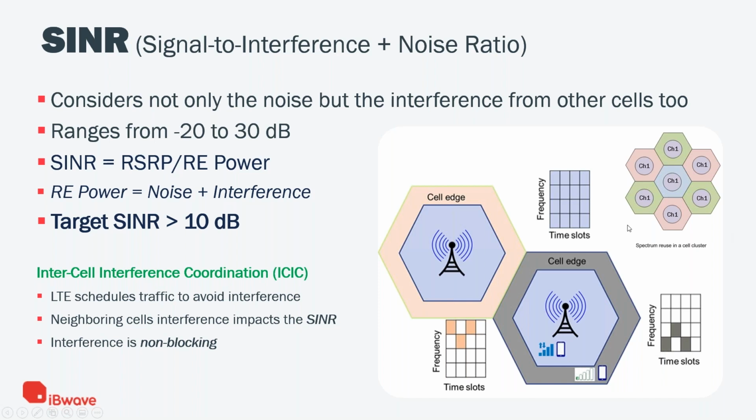So in a typical cluster where you have a one channel reuse, let's say channel 1, in reality it's EARFCN 1, but let's just name it channel 1, it's reused 7 times. So for each cell, you might see 6 interferers. And this is where you would need to coordinate when to transmit to avoid interference. But if you need all the resource blocks for whatever reason, you need maximum throughput, then you use all of them, and each resource block will give you some data, and then your throughput is dependent on your SINR.